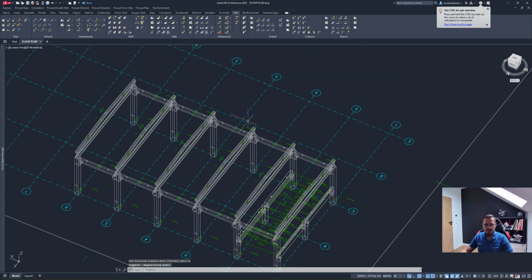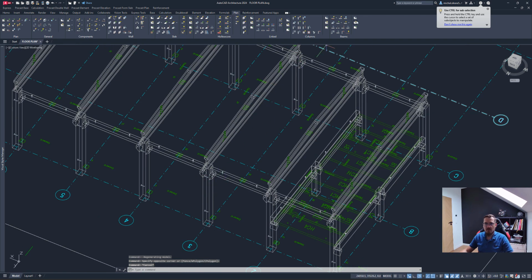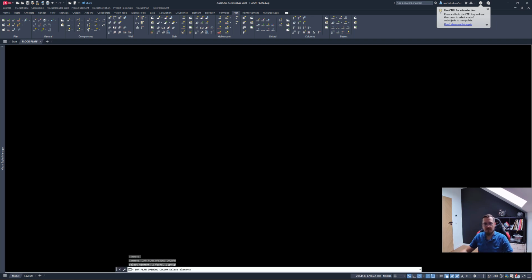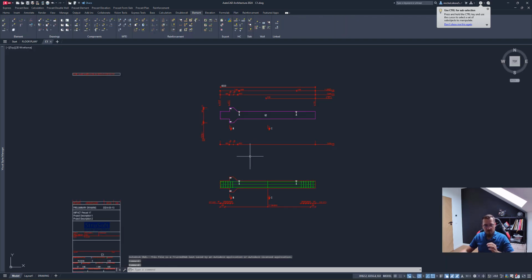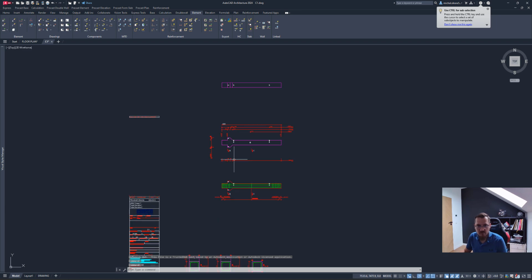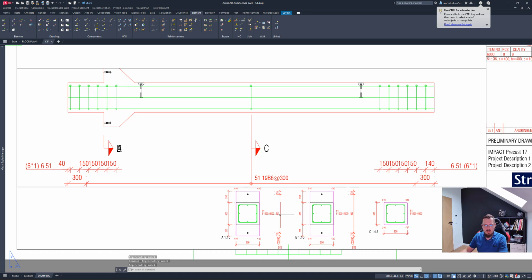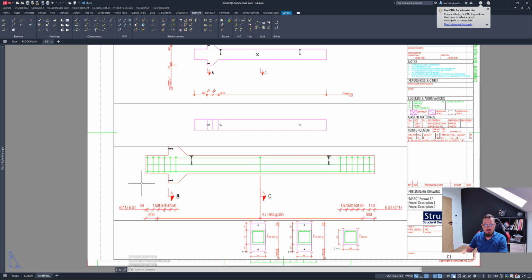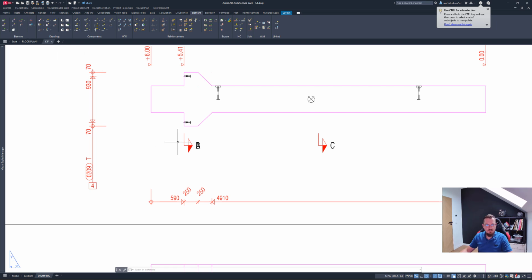Yep. Well, let's maybe select this column to see the drawing, and let's open the column drawing. That's a C1 column, so let's select this one. So I am getting a preview of the drawing. What do I get in the drawing? That depends on the template that I have. Maybe I just want one view. In this particular case, if we go to the drawing layout, we get the B sections for some reason doubled. Might be some issue with the standard.